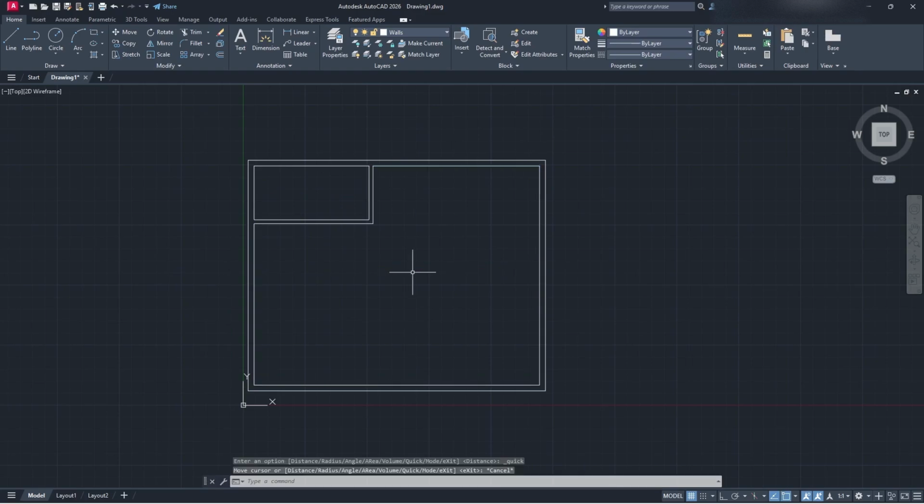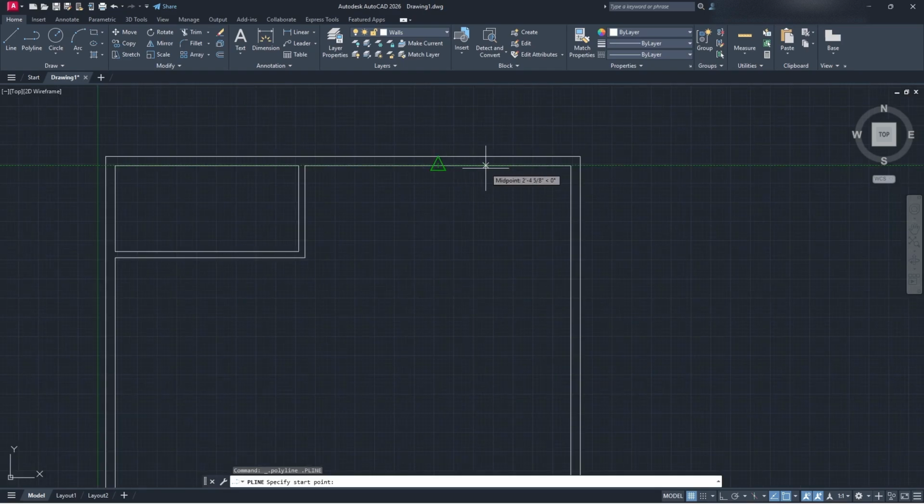So once that's done, we need to maybe create a kitchen. So I'm going to go grab my polyline tool. I'm just going to type in 53 here on my keypad to get my polyline tool going. And I want to determine how big I want my kitchen. So you know what? I'm actually going to cancel that command, and I'm going to use my line tool. So I'm going to press 55 here. And then I'm going to see, well, how far out do I want it? I'm probably going to have it about 3 feet out, you know what, 2.5. So I'll just do 2.5 feet.